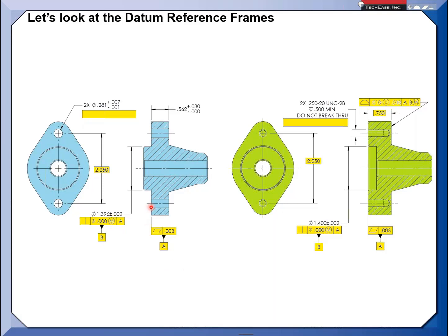You know, right now we're calling out this one plane of surface here as a primary plane, because right now all we have is a form control on how flat the points in the surface have to be within the tolerance zone. Then hopping over, in this case, to the pilot diameter, it has a relationship back to A. So you can see that this starts to become a hierarchy here, and this has a requirement that it must meet while we're establishing a relationship to datum feature A.